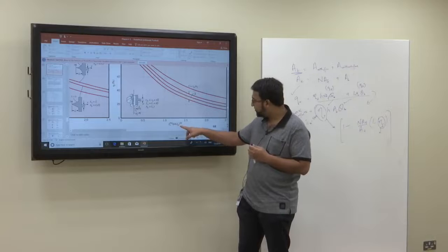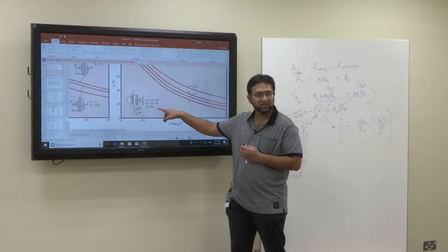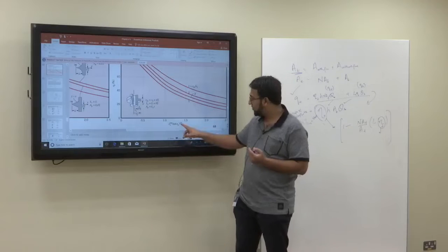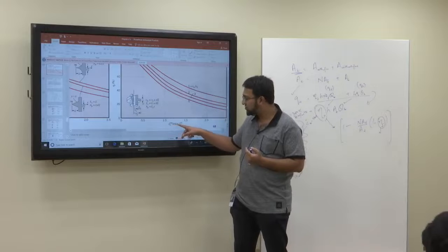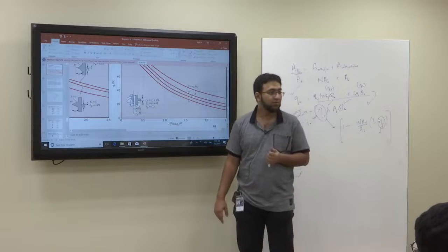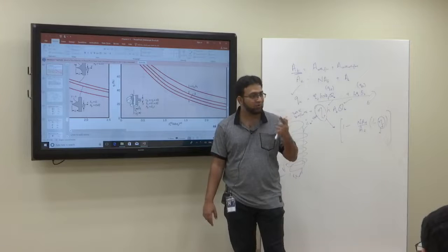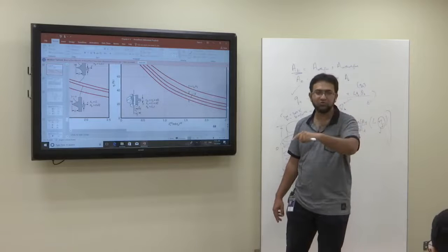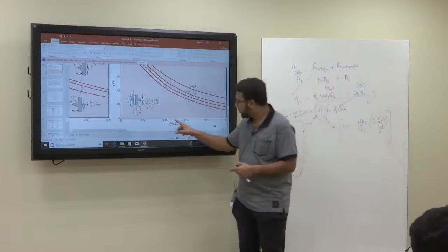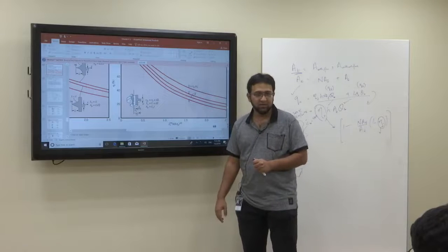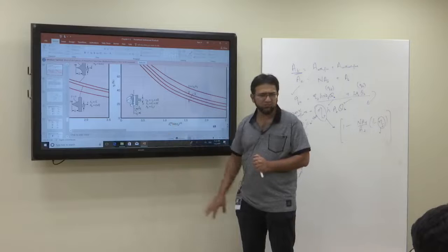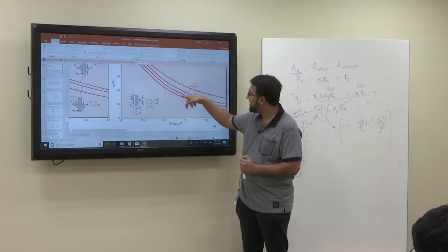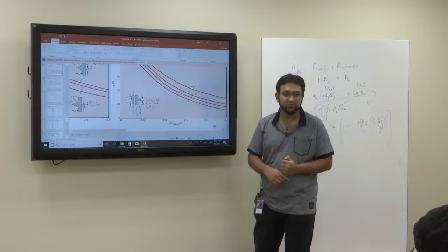What about Ap? Ap is Lc multiplied by the thickness. Now we know Lc and the thickness, so you will know Ap. So now you know Ap, you know Lc, you know h. What about k? Find it from the table. For which material? Aluminium. Exactly. So you go into the table and find the value of k. Now you know all of these terms. Once you put in all the values, you go up, and now you need to coincide with one of the curves. Which curve will you use?